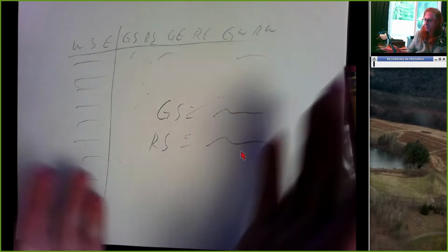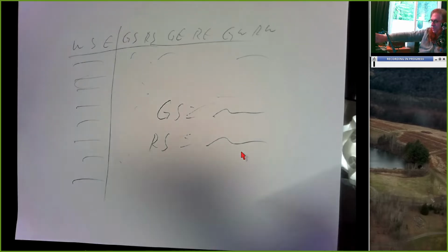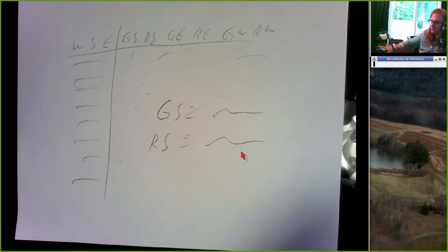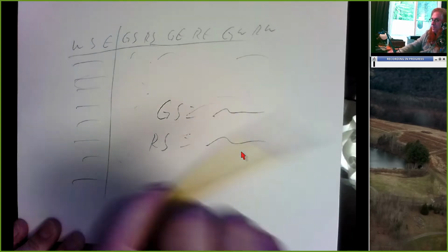And then you look at those 2 circuits that you came up with, you look at the equations, you think about the process of going through those steps, and you make a decision. And say, I'm going to go with sum of products, or I'm going to go with product of sums. And you explain your thinking or feeling for why you're making that decision. And then you toss the circuit and equations that you already came up with. You go back to the truth table and you minimize your equations.